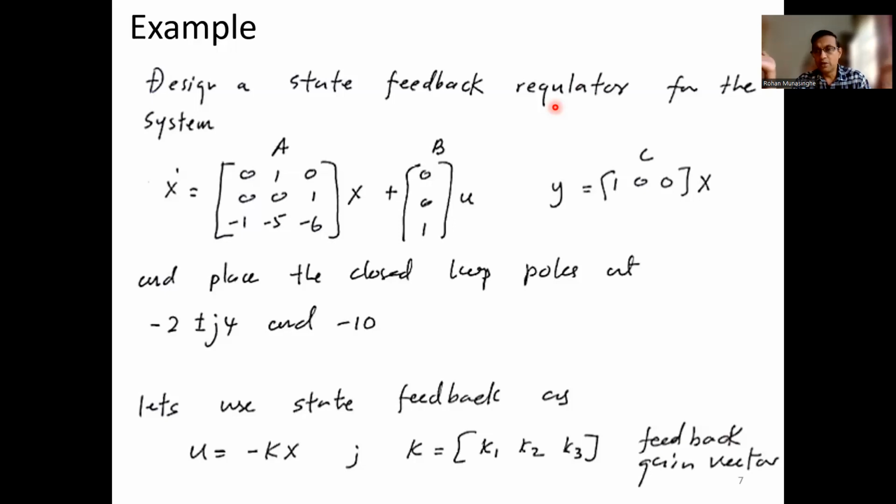But most of these voltage regulators, they only do the voltage regulation, not the frequency regulation, right? Frequency can vary a little bit, but that is done by the electrical power system. Make sure that it is 50 plus or minus maybe 1%, okay? The stabilizer is basically voltage. What it does, it makes sure you have 230 or 210 volts, right? Single phase. If it goes up, it brings it down. If it goes down, it brings it up, right? That's the whole purpose. Maintain at that level.